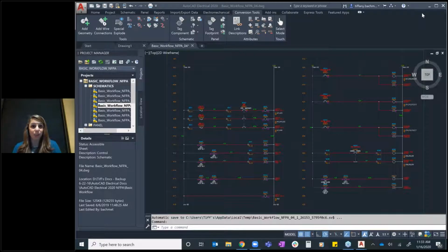So you're going to want to update those and not have those just be geometry from vanilla AutoCAD that gets ported over, right? And then I would question, do you really need the hexagon? Because you can have this be live, all the ladders update live. You don't need to do that. Or even I see a lot of people with the old grid lines of the X and Y axis grids. Now we have that in electrical as well, and it's intelligent.